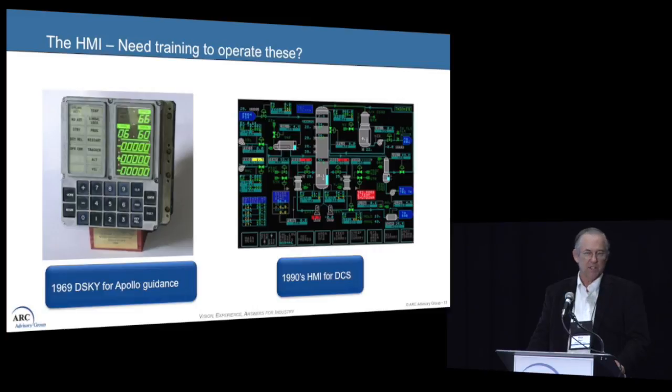So here's a common display. We still make most of our displays based on P&ID drawings, right? So these operators also need these displays. There's a lot of things that are often hidden here, overlays, certain features and functions. How are bad, out of service or disconnected points shown here, with background coloration and blinking, et cetera? And how do you navigate, and all of the standards there. There's an ISA 101 standard of how to build graphic displays. This can help. I'm not sure that standard is going to apply to the displays of the future.